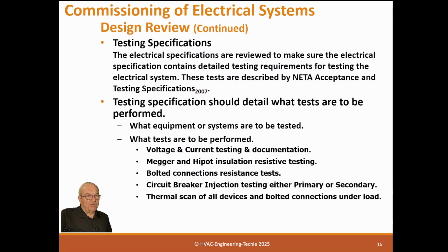Thermal scan of all devices and bolted connections under load. This is the gold standard for testing your system. A lot of commercial jobs, I don't do this, but on more critical jobs, they certainly do this. And this is where you can catch really fine details of issues before they become a big issue. Phase balance load survey to make sure the panels are all loaded between phases.